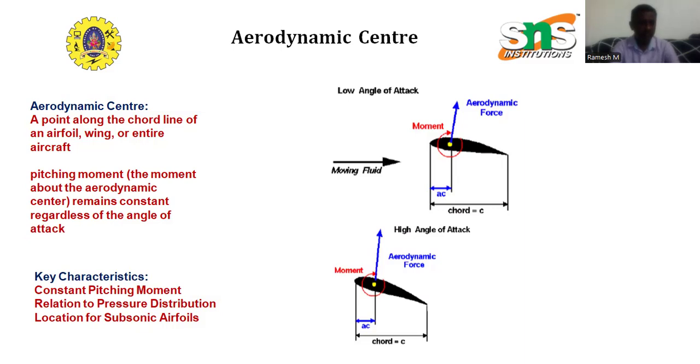As an object moves through a fluid, the velocity of the fluid varies around the surface of the object. The variation of velocity produces variation of pressure on the surface of the object. Integrating the pressure times the surface area around the body determines the aerodynamic force on the object. We can consider this force to act through the average location of the pressure on the surface of the object.